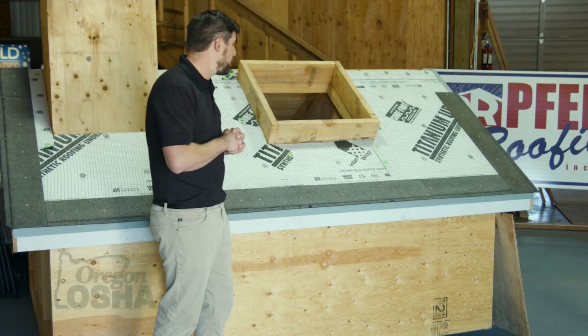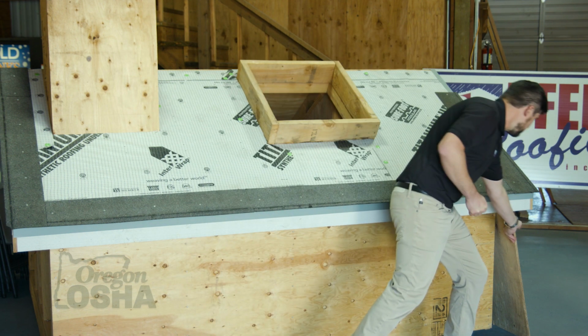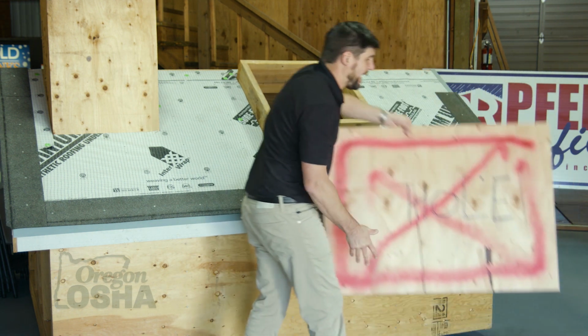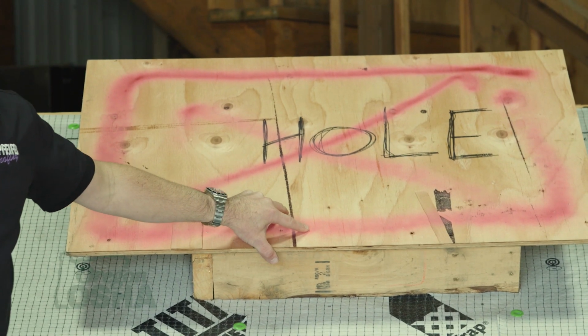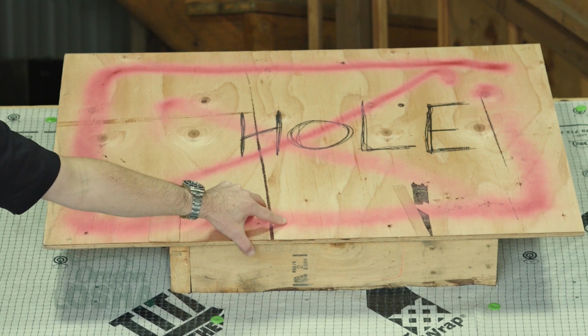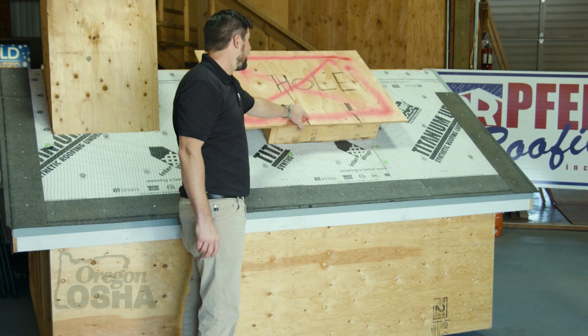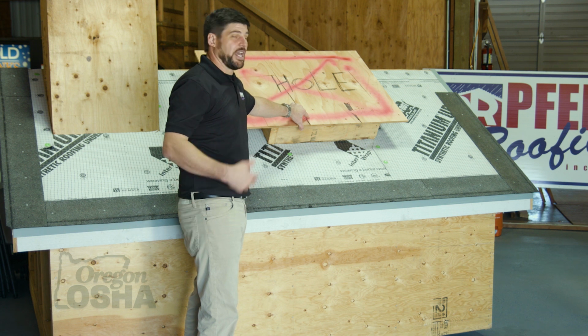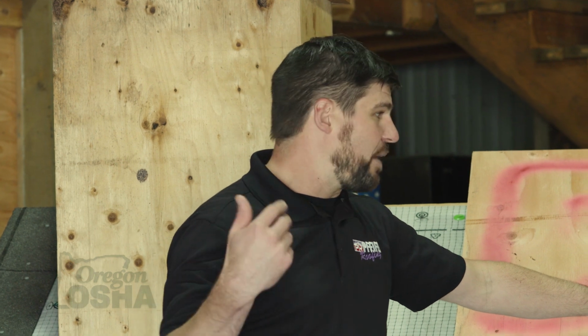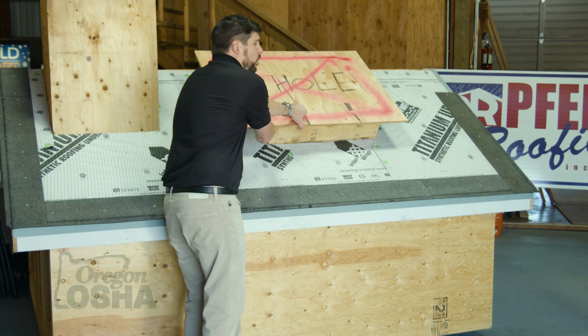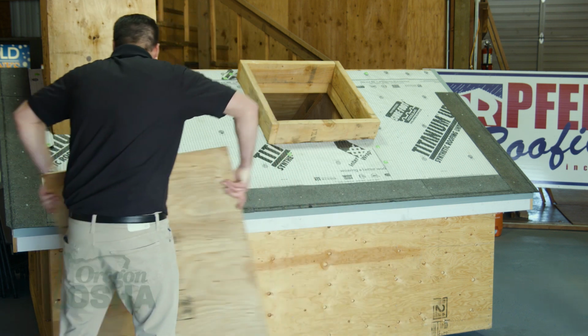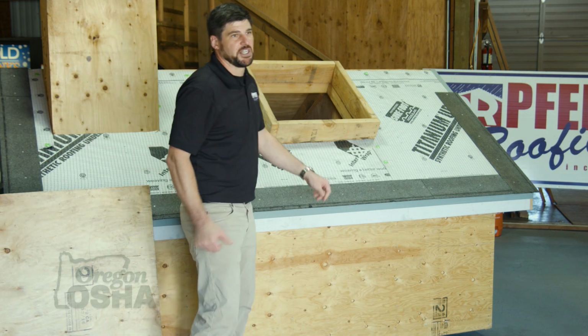It's a big hazard. What the law requires, and what we do, is when those skylights are open, you have to have a piece of plywood or something on site that you can put over the top, fasten it, and mark it as a hole, a danger, so nobody will step into it. There have been a lot of injuries over the years where people don't do this, they walk backwards not knowing where it is, and they trip and fall. Some people have even died. So it's really important to take the time to cover the holes on roofs, whether it's new construction or even a residential re-roof.